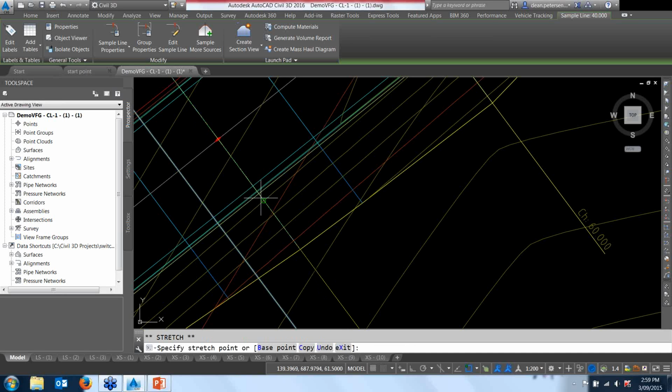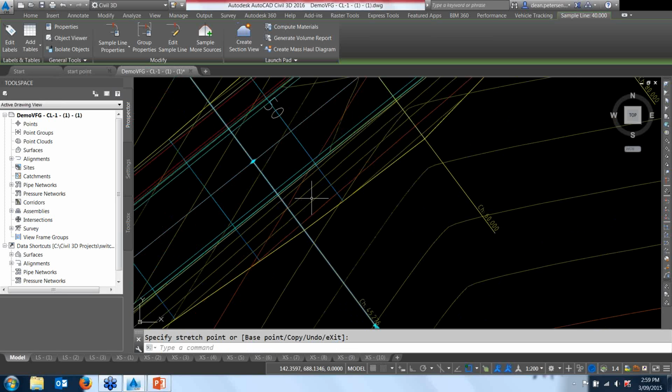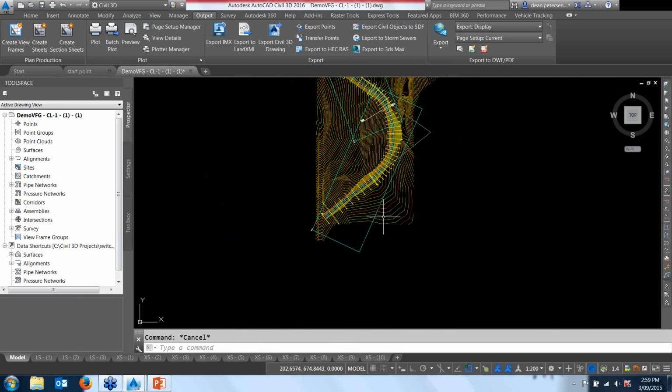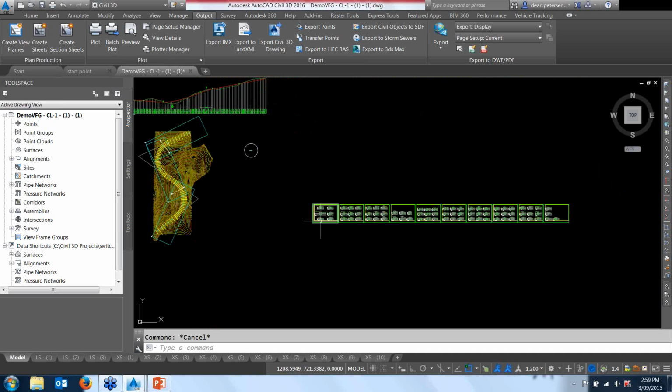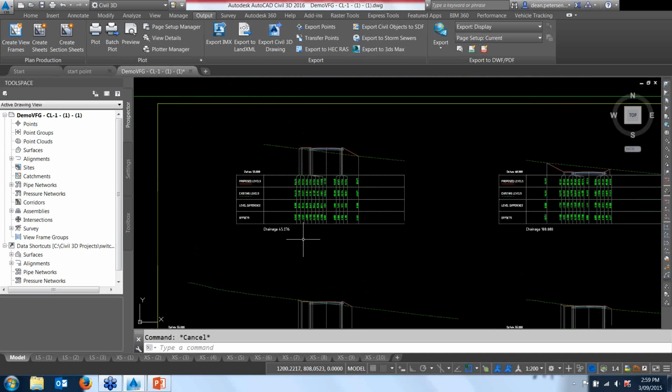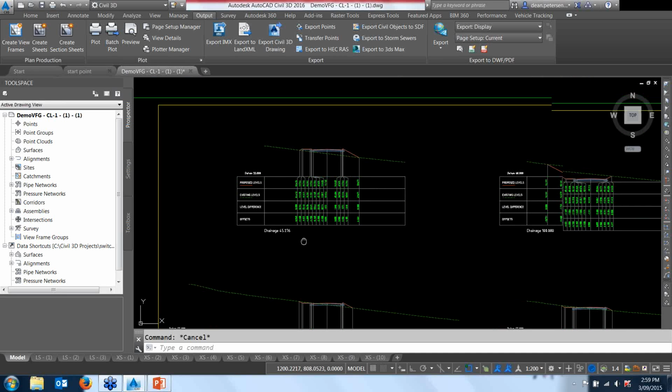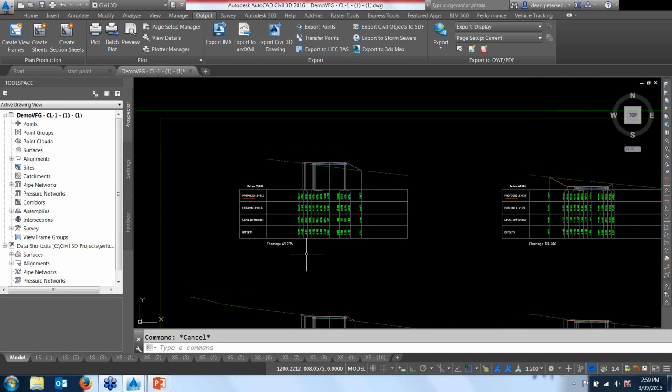And then move it back and snap it to there using the O-snaps. There we go, it's fixed it up. If you made these frequency lines everywhere you want a cross section before you actually come into here, you don't need to do it after the fact. But that's how you fix those up if you ever see those.